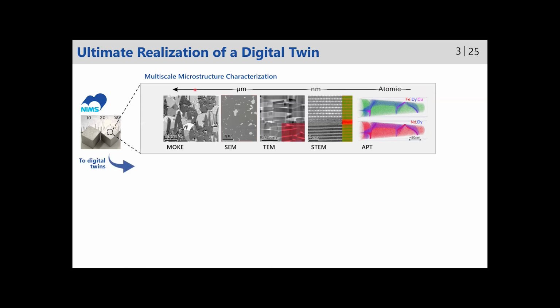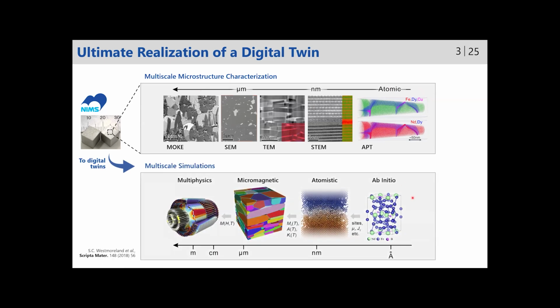And ideally, if we would like to construct the ultimate digital twin, we should also be able to describe materials starting from the atomic arrangement, local properties, intrinsic properties, such as, in the case of magnetic materials, what is the long-range magnetic ordering, what is magnetic anisotropy related to the crystal structure, and other intrinsic properties. And then at the atomistic level, how this is organized at the interfaces, how domain walls interact, for example, with different point defects and other crystallographic features.